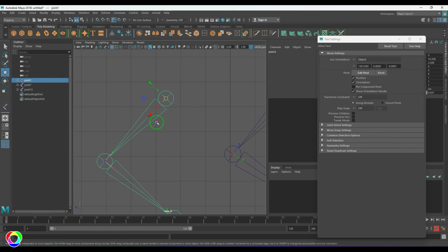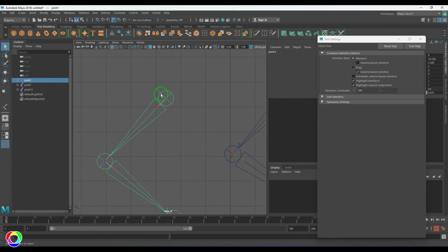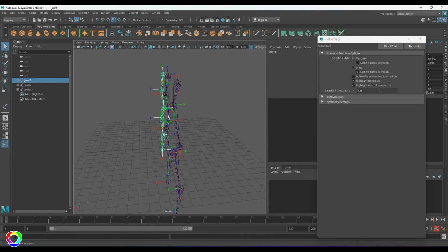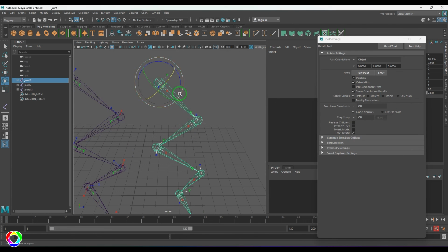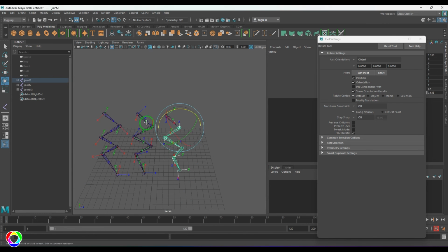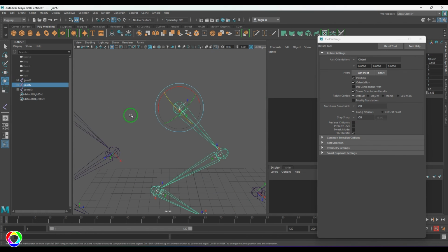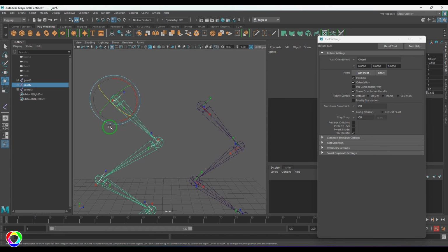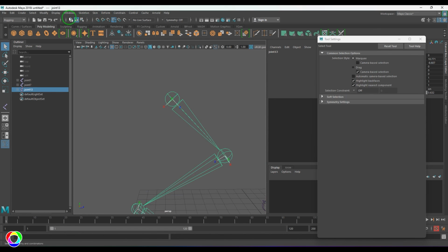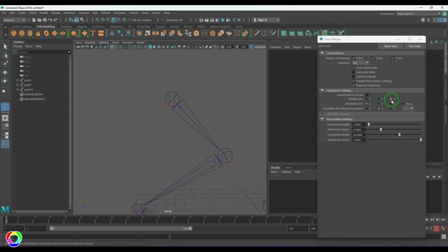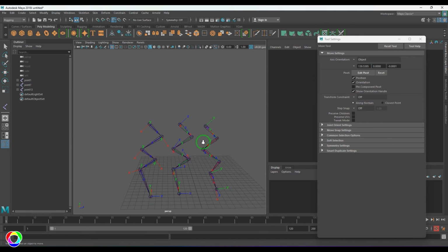You should be able to see here the primary axis is the X axis and the secondary is the Y axis here. Okay, so what is the primary axis going to do? Primary axis is going to twist, and the secondary axis is going to open up the joint. Okay, just like a knee. And very similarly here we got the primary as Y and secondary as Z. In both these cases the secondary is facing upside, right? But in the third setup, I have chosen the secondary as X, but X is facing towards the Y negative side. You could see that is facing down there.